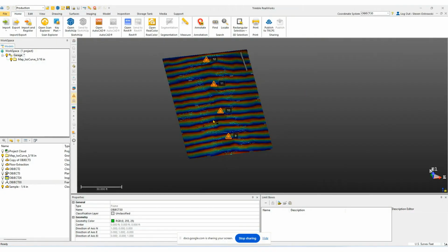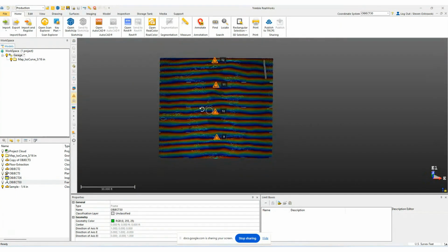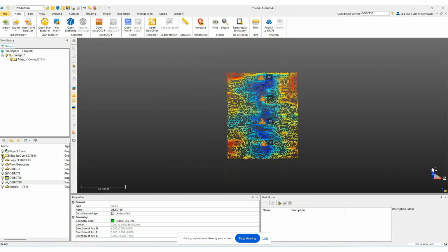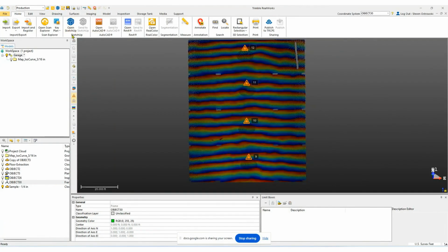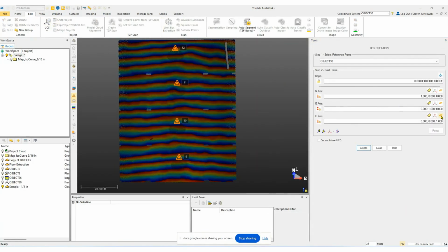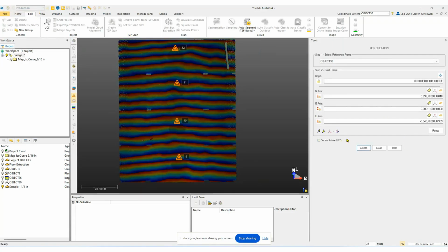Again, you could do something similar with a user defined plane or an inspection in FieldLink, but this is going to give me a little bit better numbers. So if I close this, this is actually the contours we created in the video right before this on just fitting a plane. But with the suggestion from Jason Hayes, who is the RealWorks expert, what we can do is instead use the UCS. And then I clicked create from plane, which will fit to that for the elevation. And then if I close that, you can see this is essentially best fitting that same plane.